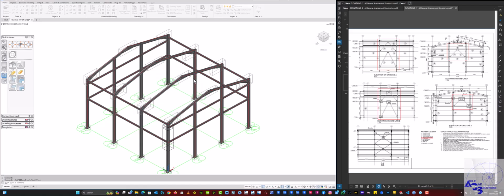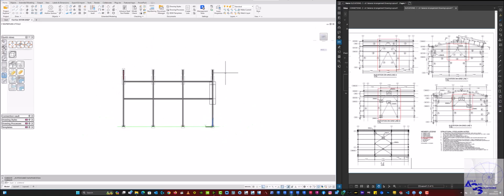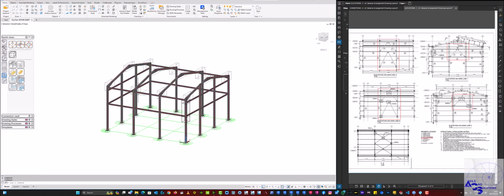All right, so from there, let's sort out our UCS. So I want my UCS to be in this view. For my UCS to be in this view, I just locate a middle point that approximates the middle point of the grid. You will notice why. You can put it at any point along the grid, it doesn't matter, but I prefer my things to be central, working from the center going outwards.